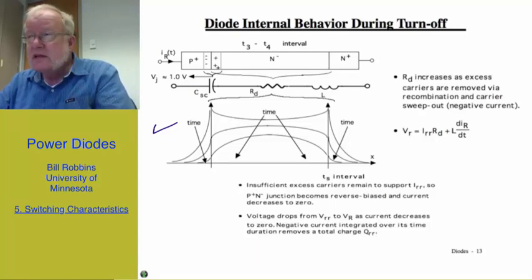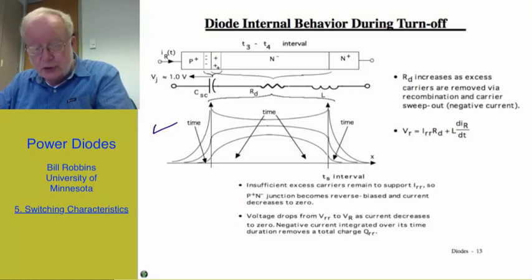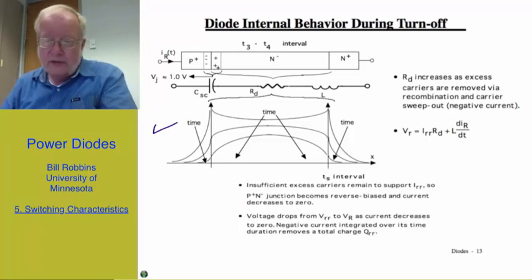And so in that case, where we may exceed the breakdown rating of the diode, we're going to have to do something. That could be either in the form of using diodes that have higher ratings, and secondly have a softer switching characteristic, not so abrupt. In other words, the time T5 is larger, or we may have to put in special circuit components to implement what we call a snubber to prevent the voltage from being so large.